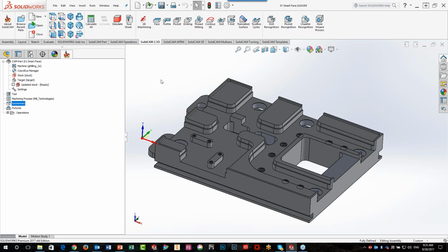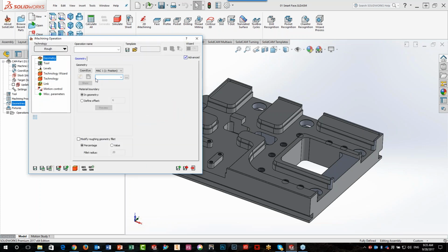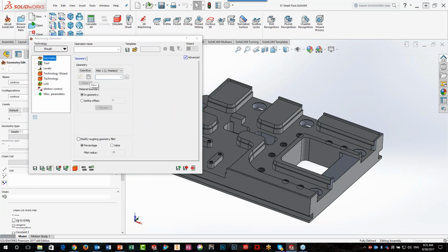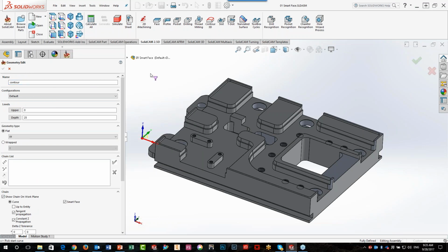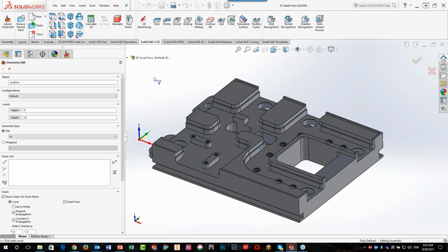And when we create the geometry, and I'll use iMachining for this particular case, what we normally have to do is, you note that I have this pocket over here, which has open edges on it. I also have islands inside this area that create geometries around those islands. I have a semi-open area over here, so I have to create a geometry around that. I have holes, which I do not want to create geometry around.